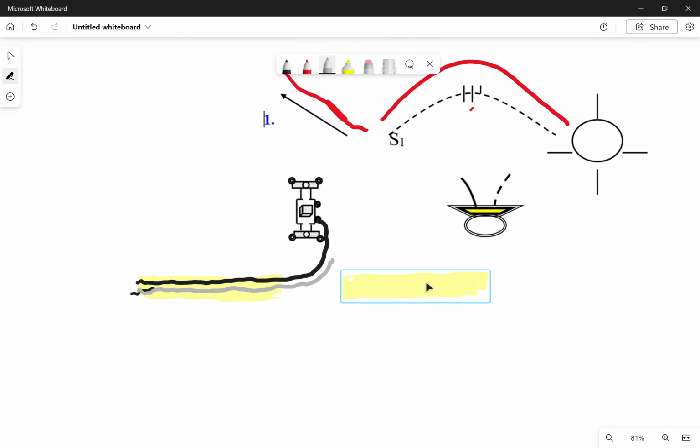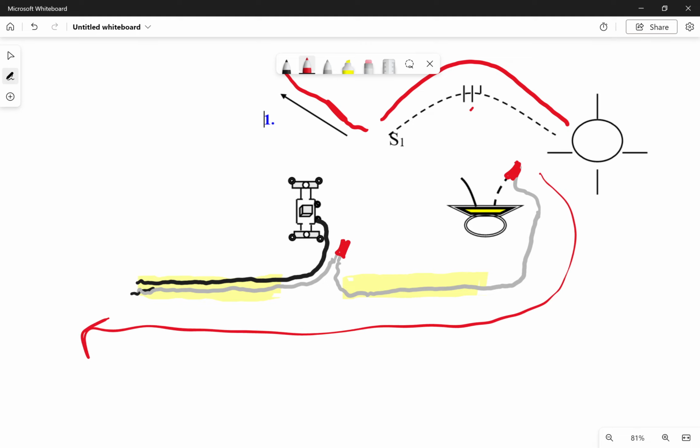Well, we've already broken it, right? Because we're using more than one piece of cable here, we're not using a single piece of cable. This white wire has already been broken and it's not connected to our light bulb. All we're going to do here is take a wire nut and connect here and here, and use this wire nut to make sure that that bond is good. So our path for our white wire is going to go all the way back to our panel.